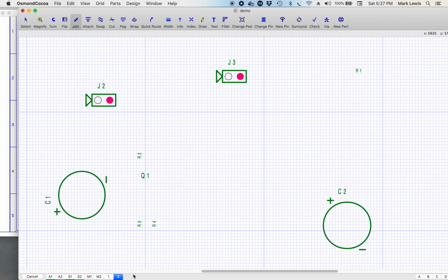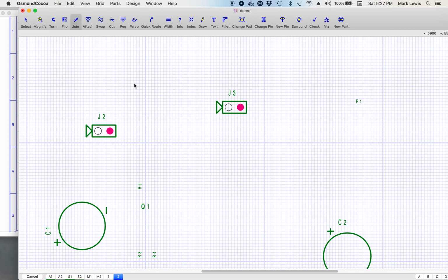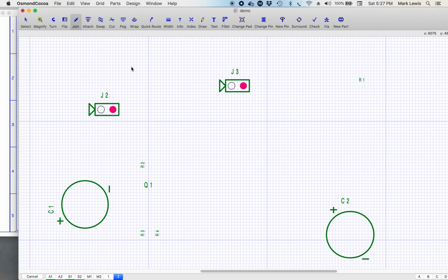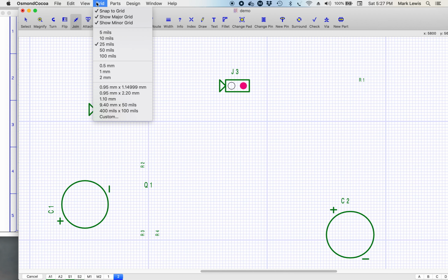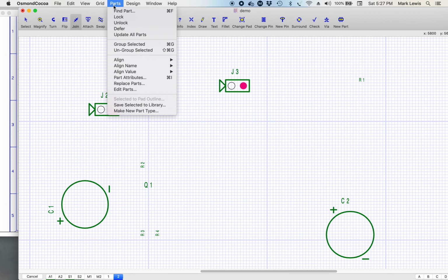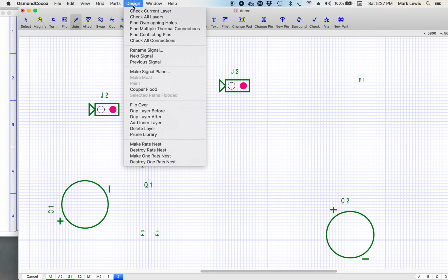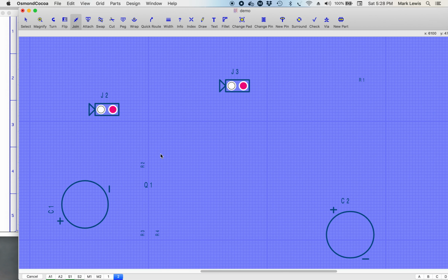A lot of the boards I design are 4 or 6 layers or whatnot. Let's suppose I want to make this whole bottom side all copper. So everything on the bottom of this, unless it's some type of trace that's isolated, the trace is like a wire. I got to go to where it says make, where are we at? Copper flood. If I go to copper flood, there we go. The color's right this time. Some of them I've had to change because it didn't show up. This whole bottom side of the circuit board that's blue is all going to be a copper surface.